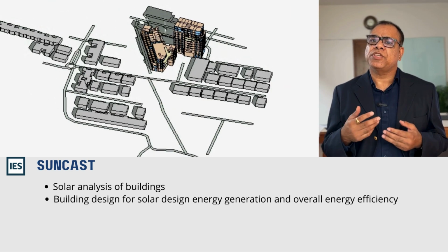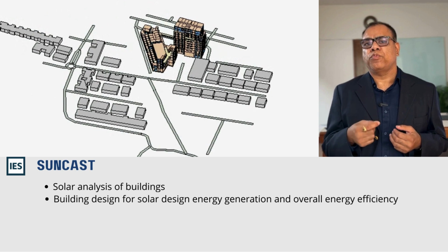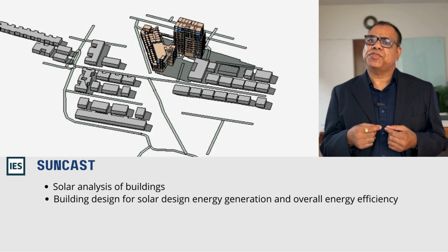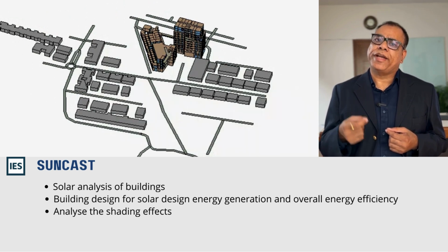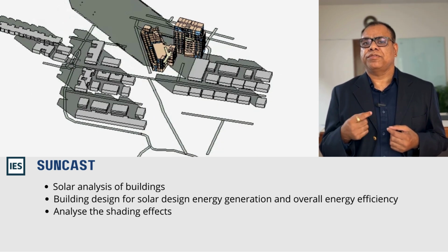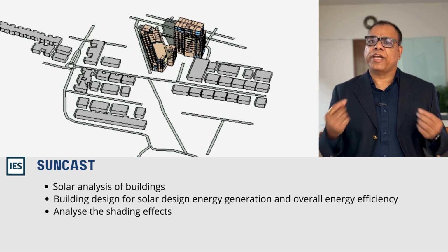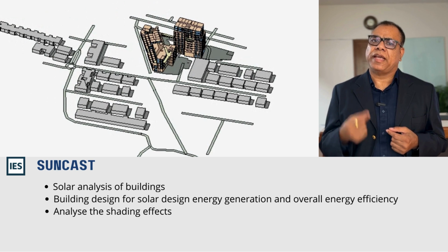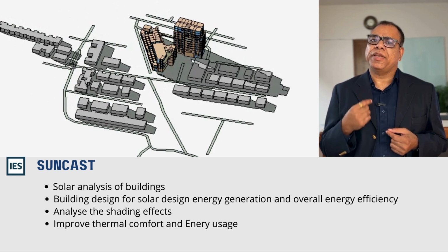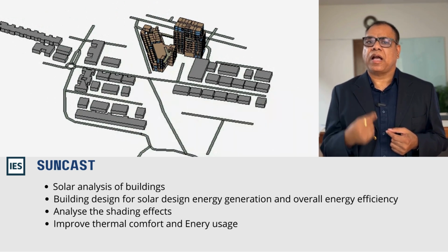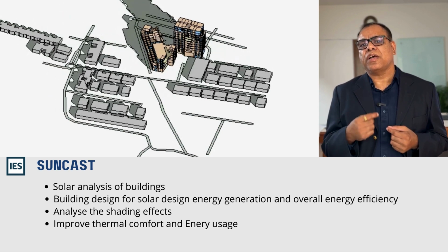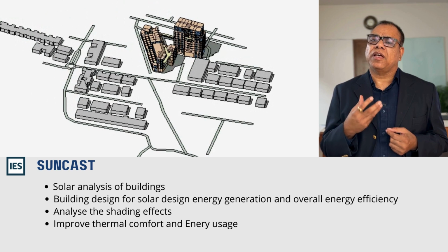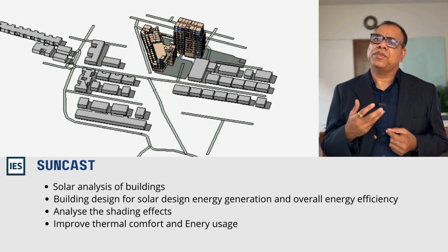Sometimes you need shadow to protect the building from the external heat gains, and sometimes you want to avoid shadows, because you want to have the overview or outside view. So both things you want to analyze with the sun path diagram, and that is the application which is known as Suncast.